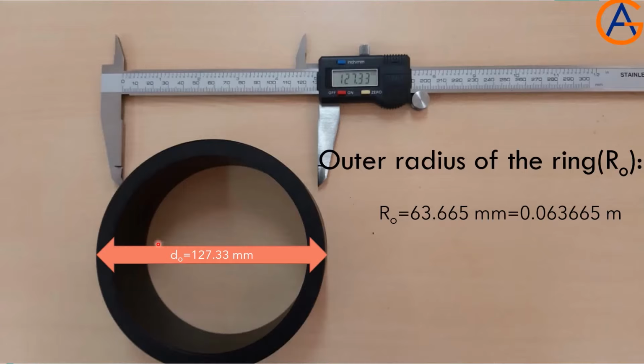Now the outer diameter of the ring is 127.33 millimeters. Again we measured with the digital vernier calipers. Divide this number by 2 so that we get only the radius, which is equal to 63.665 millimeters. Divide this number by 1000. So this is the answer.